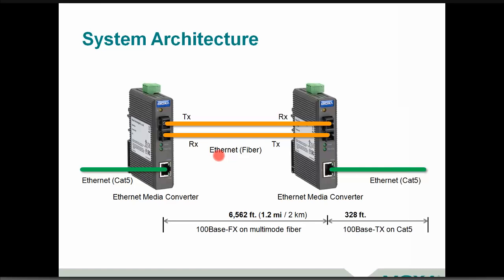One thing to point out here, you will note that there are actually 2 fibers used for most technologies, or most applications. One is a transmit and one is a receive. So this one here transmits to this one to receive, and this one transmits back to receive over here. So one for transmit, one for receive, kind of swapping those cables amongst the media converters. Both are the same media converter and used in this configuration.